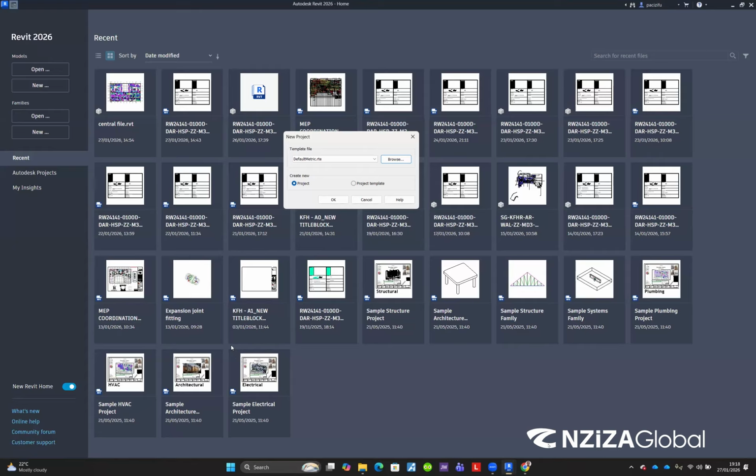If you open it and you see there are inches and other things, you just open the imperial template. You just need to set the units, then change it into the unit that you use.